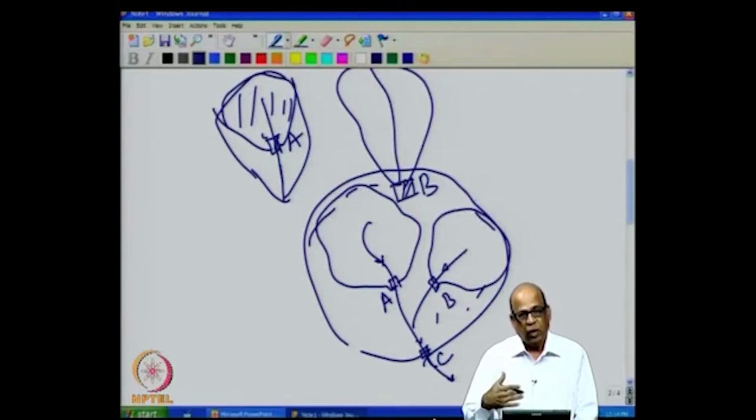In other words, the complete gamut of the hydrologic variables that contribute to runoff generation are the same for all these catchments, in which case the response of these catchments will be the same for a given precipitation pattern, and then we say that these are hydrologically homogeneous catchments.